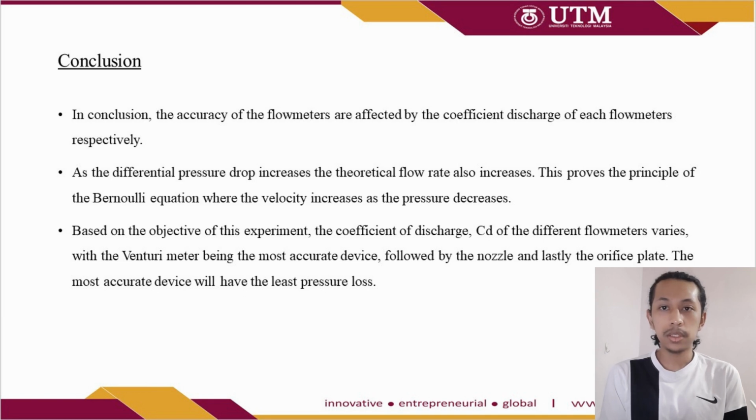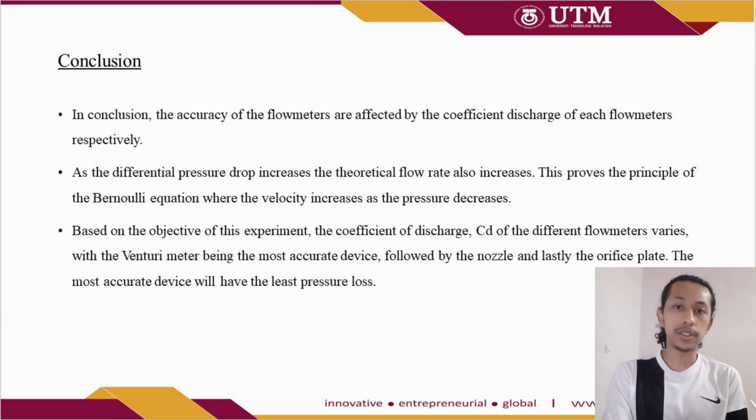For the conclusion, we can conclude that the accuracy of the flow meters is affected by the discharge coefficient of each flow meter respectively, and as the differential pressure increases, the theoretical flow also increases, and this proves the principle of the Bernoulli equation, where the velocity increases as the pressure decreases.